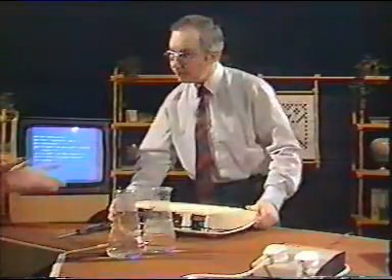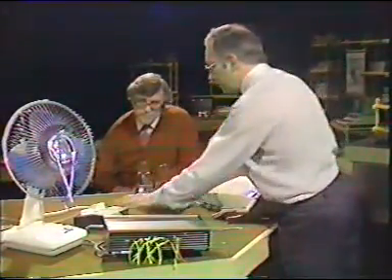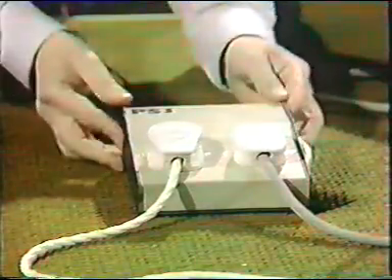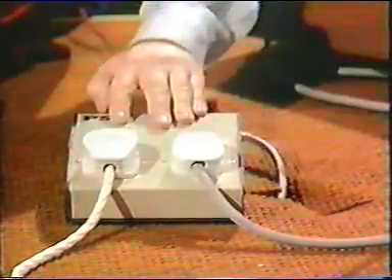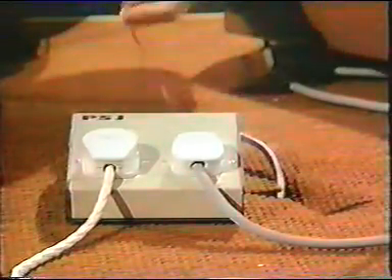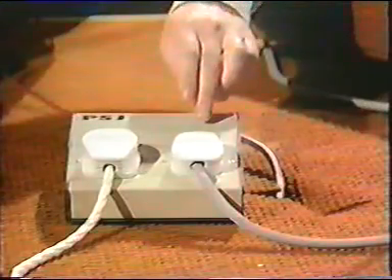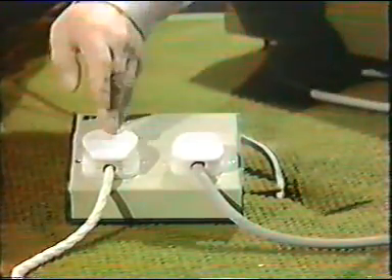That's the same output port we used for those lights that were going on. Exactly the same, that's right. We've got the control box over here, and all it does is mains comes in to the control box, as does the feed from the computer. And the feed from the computer is used to switch on and off 2 relays, one to turn the heater on and the other to turn the fan on.